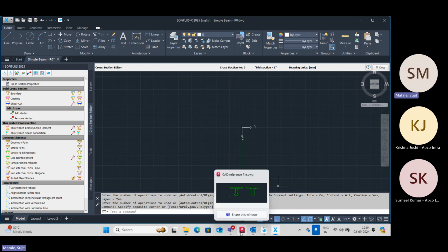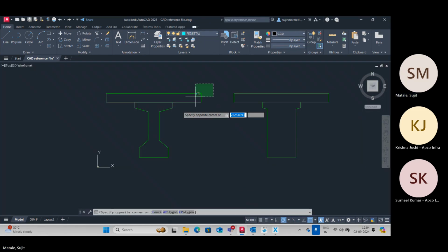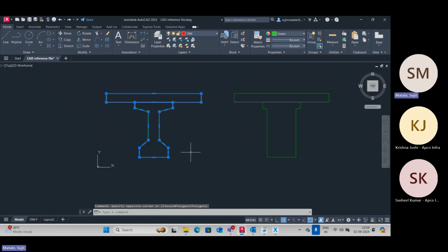You need to go to your AutoCAD file and select your midsection. Now you would want to copy it from this environment to the other environment, right? Instead of doing only Control C, if you do Control Shift C, it will ask you for the base point for selection and base point for insertion, which is a controlled approach. So I go with Control Shift C.